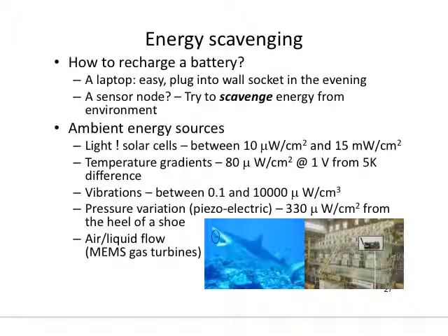You need some statistics on the amount of energy that you get every now and then, and predict the amount of energy that you will receive during a specific duration of time, and plan your energy consumption based on that. That affects both the sensing frequency and the communication. The communication protocol needs to be aware of this. The sensing needs to be aware of this, right? So you need to change everything based on the type of energy that you are harvesting.